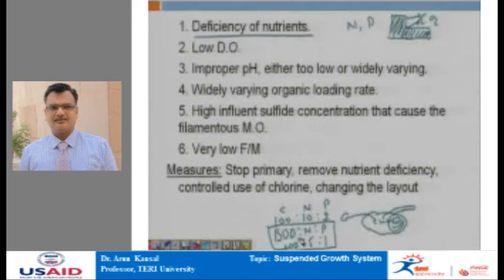Now, for some reason, such as excessive dilution of the wastewater, or certain industrial discharge having a very high level of BOD but a low level of nitrogen and phosphorus entering the wastewater, we have a deficiency of nutrients like nitrogen and phosphorus. That is, we have more BOD as compared to nitrogen and phosphorus, as dictated by this ratio. In such a situation, the organisms which develop within the aeration tank are the ones which have more surface area. We call these organisms filamentous organisms.